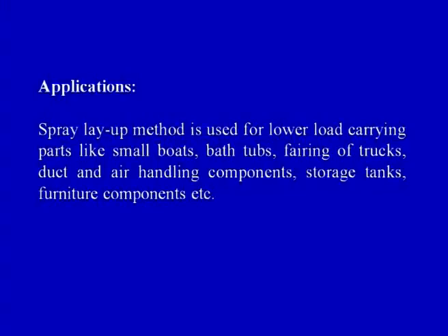The applications for the spray layup process are as follows: the spray layup method is used for lower load carrying parts. Lower load carrying parts should be emphasized, because, again, we have already seen that the mechanical properties that we get from a spray layup composite are relatively inferior to the properties that we get from the hand layup product. So a composite product made by the hand layup process would offer us better mechanical properties as compared to a product made by the spray layup process.